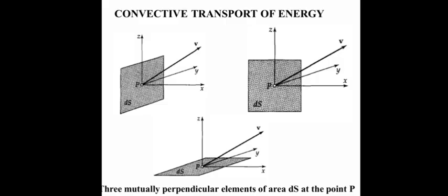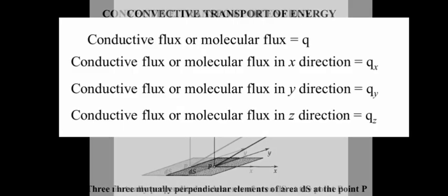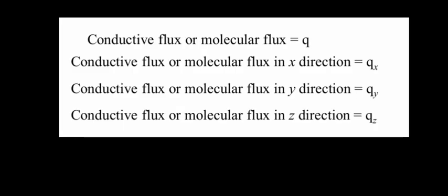This relates to the stresses within the fluid and the work done by these stresses as the fluid moves and deforms. Think of friction between layers of a moving fluid generating heat. This is linked to the work done at the molecular level. Finally, there's conductive flux, also known as molecular flux, which represents the transfer of energy due to random motion and interaction of molecules, typically driven by temperature gradients. This is what we commonly understand as heat conduction.